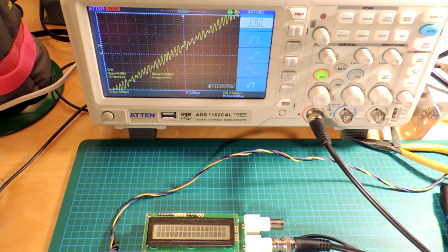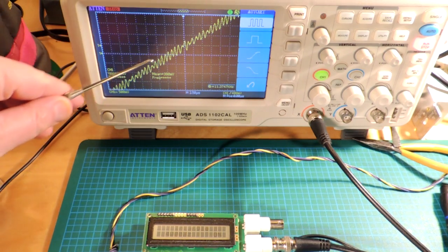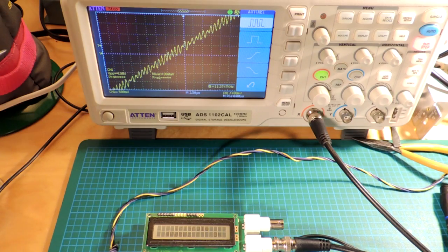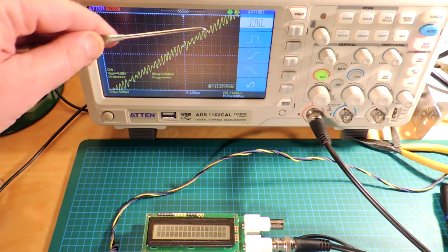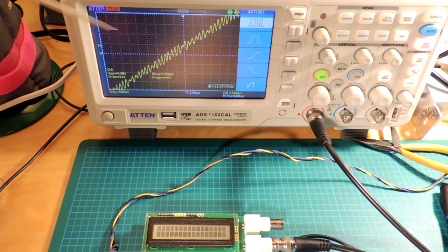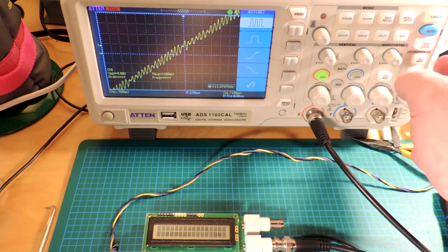Essentially, they haven't done one or two things. They haven't isolated the digital ground from the processor adequately from the analog section. You can see that there's no plane management on the thing, nor do they have a decent filter on the output stage. So kind of a fundamental error you can make easily on a digitally synthesized signal generator. And there you go, it's present here, of course, so a beginner's error.